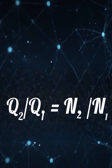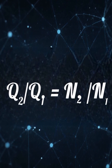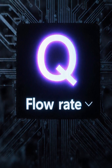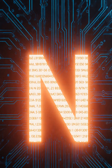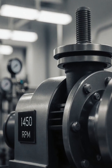Mathematically, this direct proportionality is expressed as Q2 divided by Q1 equals N2 divided by N1. Here, Q represents the flow rate of the fluid, and N denotes the rotational speed of the pump, crucial for output adjustment.